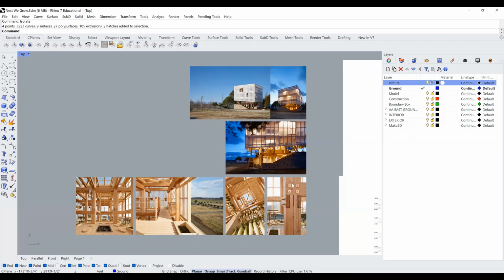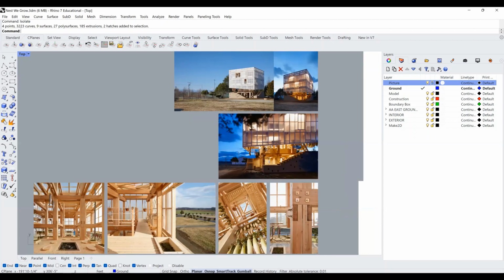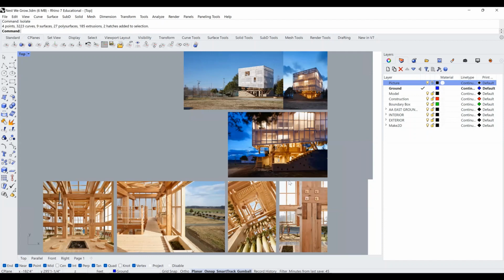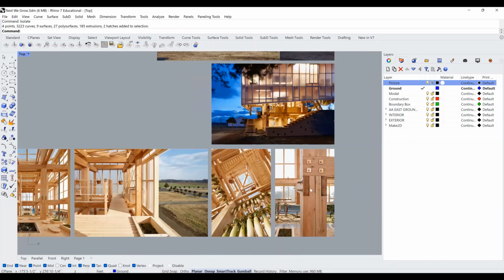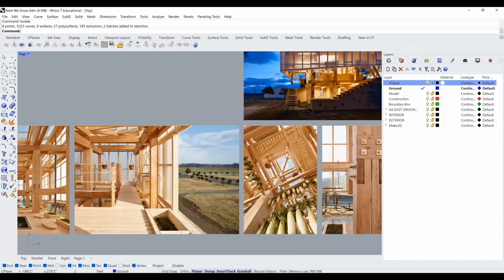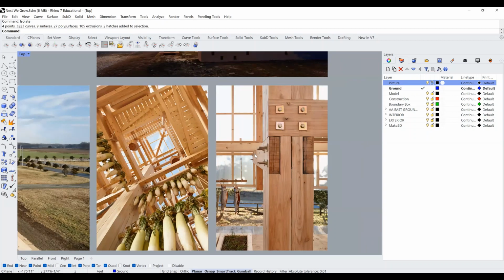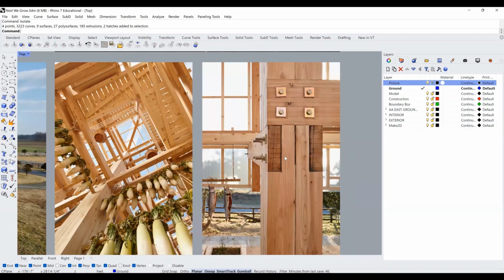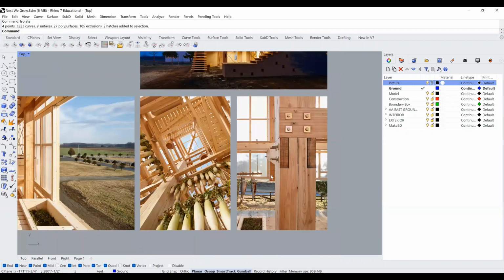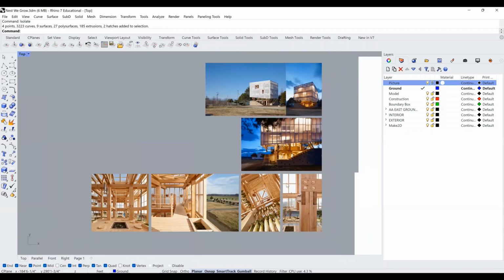As we look at this pavilion in more detail, this wooden pavilion to be exact, we notice that it is built out of several wooden members. For example, this column is comprised of multiple wooden members that are intersected by this beam that is also notched within the column itself, right? We'll be using this to investigate different kinds of conditions and how they're treated within the pavilion and your pavilion too. This can mean a floor to wall type of condition, or a wall to a ceiling type of condition, or a wall to ground type of condition.